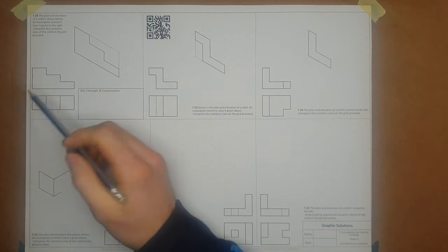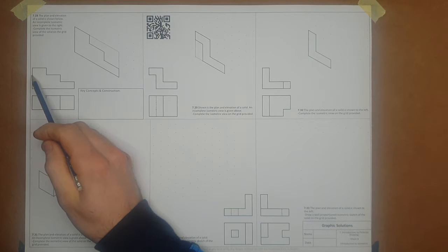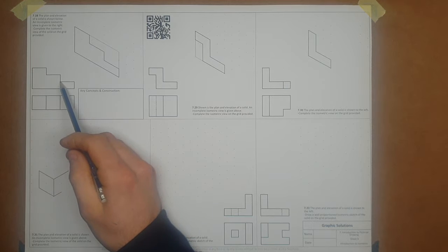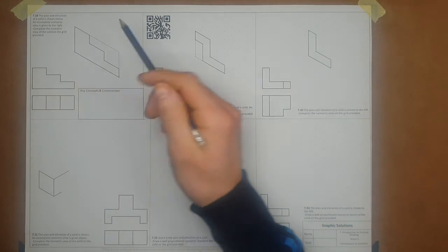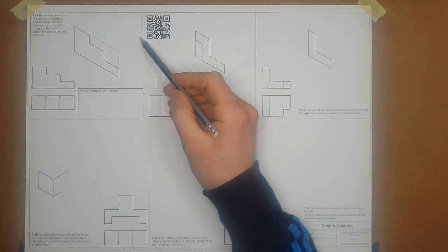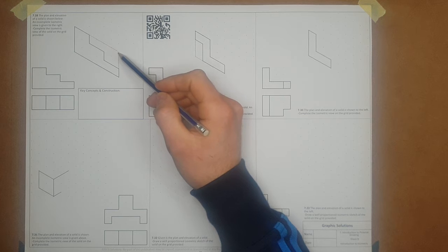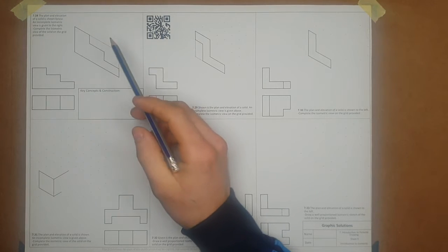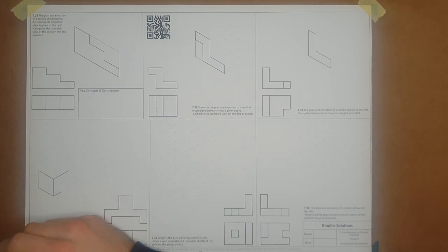We're just going to be doing this now, and we'll be counting the boxes. When we're starting here, the length of the steps is two boxes long, and we'll be applying it along an isometric grid. So isometric means 30 degrees left, 30 degrees right, and vertical. They're the 3 angles we'll be marking. When we get on to more complex drawings, there will be curves and slopes put in, and that will change what we're doing slightly, but everything on this page will be nice and easy to work with. Just do a little bit of freehand sketching. All 6 of these, all freehand sketched.